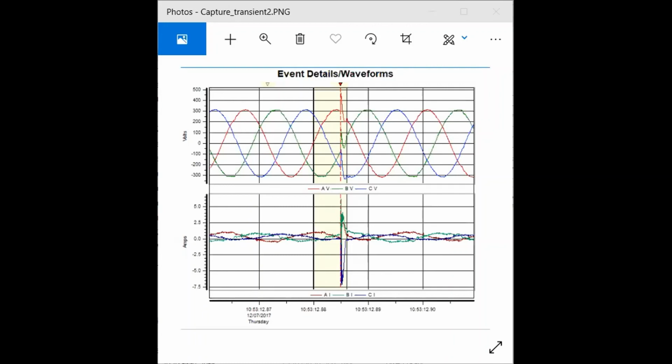So you'll see there's a relationship between voltage and current here, and it's important to understand that. One of the big changes with IEC 61000-4-30 edition 3 is that current is treated the same as voltage. Prior to that, voltage was only monitored. From Dranetz's perspective, we've always treated current just like voltage, so it was no big deal for edition 3 for us. But it officially says now in 61000-4-30 edition 3 that you shall measure the current in the same way that you measure the voltage. For situations like this, it's for RMS events, but because of that relationship, you are looking at a closed circuit here. So you will see voltage affect the current and current affect the voltage.